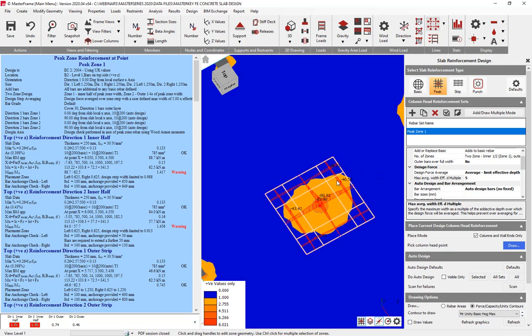One of the concepts to get your head around is that we are moving beyond the concept of traditional column strip, middle strip, because those types of adages, whilst they were useful when we were doing equivalent frame analysis methodology for placement of reinforcement, we aren't necessarily bound to those principles anymore, and we really can do whatever we want within sound engineering principles.